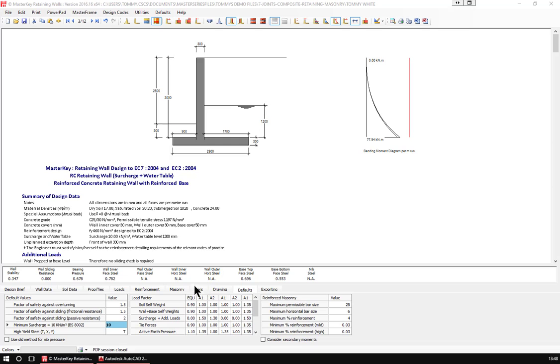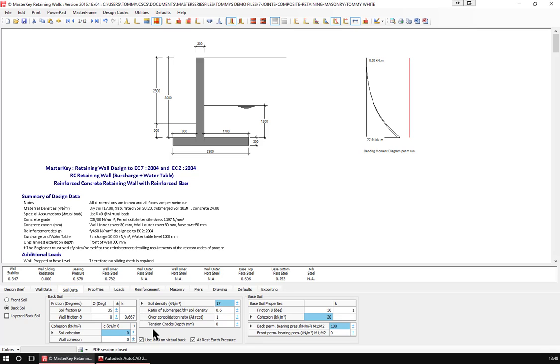But we do also have the facilities to do the cracking, and I'm just looking at soil data. There we go, tension crack depth for the back soil. And if I said I had 500 deep tension cracks, then that adjusts everything down, because then the water table's below that in the first place. But I always get nervous, thinking about not having any water here at all. It's just my cautious nature. But just take that back off. So yes, tension cracks.